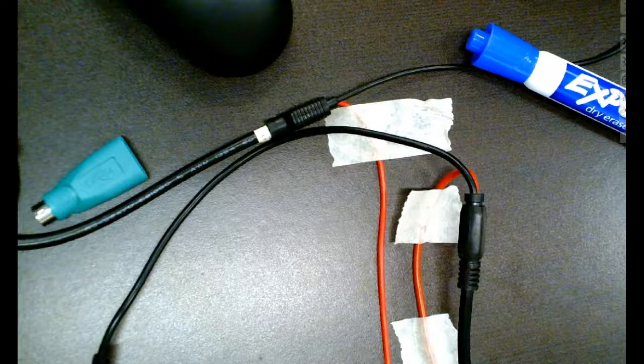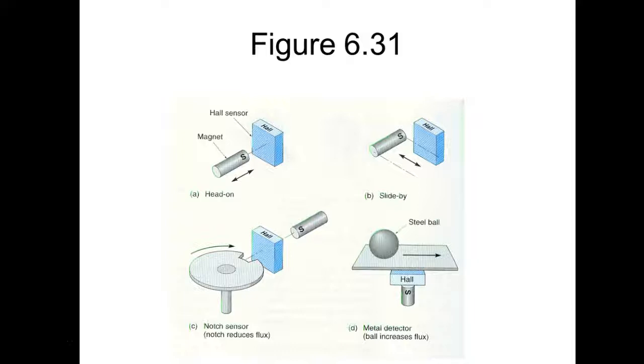So these guys sense magnetic fields. They're very similar to a magnetic reed switch. But what advantages do these have? They're cheap. But they're not as cheap as some reed switches, right? You understand that? The advantage of these guys is that they absolutely have no moving parts. So the only thing that'll fail on these things is electrically. A magnetic reed switch could fail either electrically or mechanically. Just like your car is an electromechanical device.